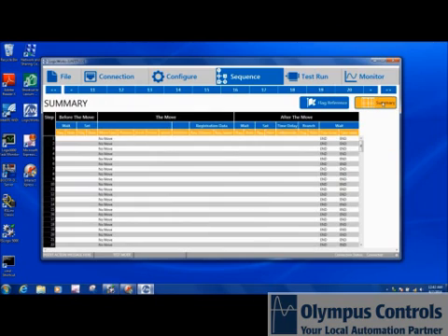and then your PLC can call what step in the sequence it wants to run. So if you didn't want to use the Yaskawa motion instructions, then you could use the Yaskawa sequence instruction, and you could just tell it to go to these different sequences, which are different moves. Either way works just fine.